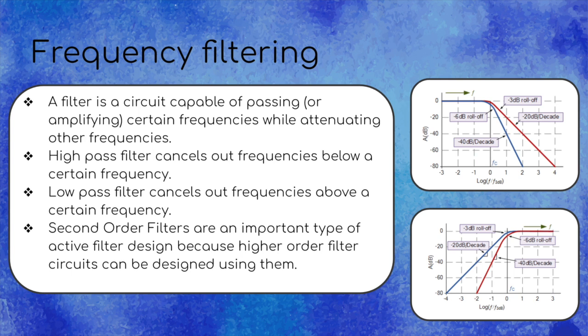They are sometimes referred to as VCVS filters because the op-amp is used as a voltage-controlled voltage source amplifier. Using a second-order filter is recommended in our case as they provide a roll-off of 40 dB per decade as compared to 20 dB per decade provided by first-order filters. In these filters, the use of active components will separate the filter from the rest of the circuitry. Therefore, due to the greater amount of noise inherent in unfiltered EMG, we wanted to build these filters without any gain.